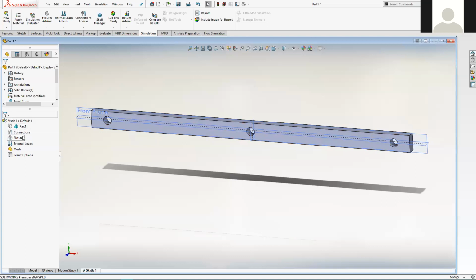So unless you need something quite unique that's not in there, it's often good to use the ones that are provided. I'm not saying that it's not wise to check on the values sometimes. If you're making something that's highly mission critical, it would be wise to use more than one source of, let's say, the Young's modulus. So maybe go away and just verify that SolidWorks hasn't got it wrong. But anyway, for these examples, we're just going to pick from the library that's actually in there.